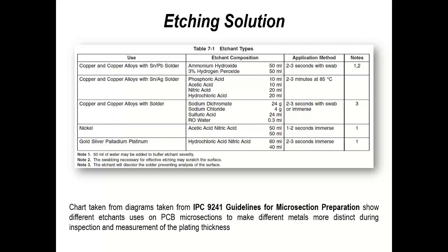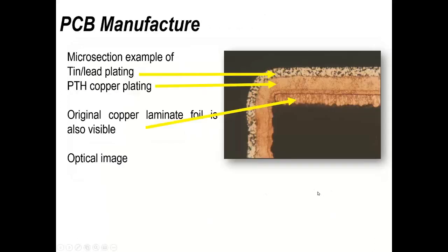So when you've got an etching compound that you use, you're cleaning the sample first of all, you're putting it into the etching compound, but it's only in there for a couple of seconds, 2 or 3 seconds. It's out, you wash it in clean water, preferably warm water, and then that stops the etching operation, because you can over etch a sample and you will certainly see the grooves, the differences, but they will be exaggerated because remember, it's etching away metal to show you the differences in those surfaces. So you're only really etching for a few seconds to get the result that you actually want.